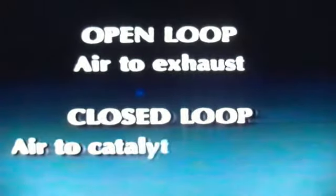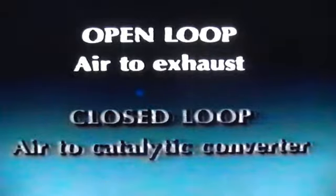In open loop, the air will be going to the exhaust. In closed loop, the air goes to the catalytic converter. Since for our tests we're in open loop, you should feel the air going to the exhaust. These tests may seem unimportant, but as we've mentioned before, making them can solve a lot of your customers' cold drivability problems. The next component that needs to be checked is the oxygen sensor.